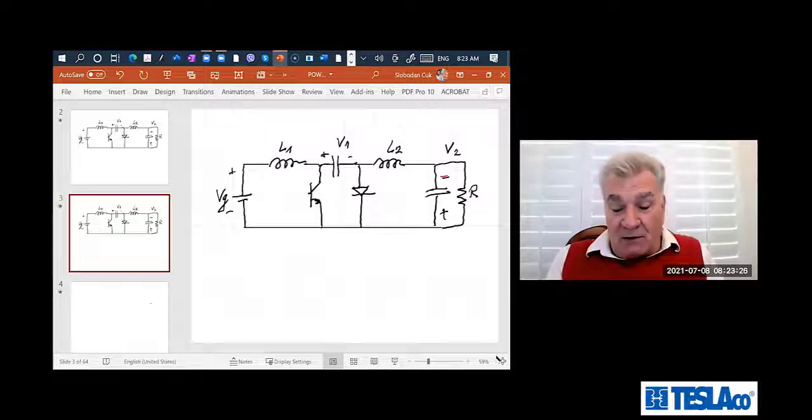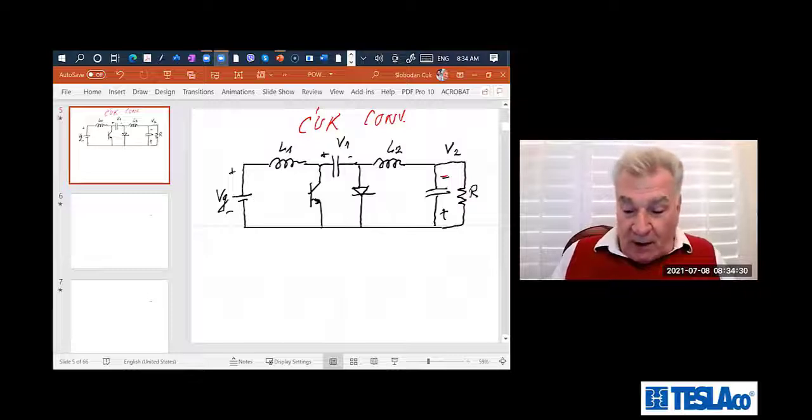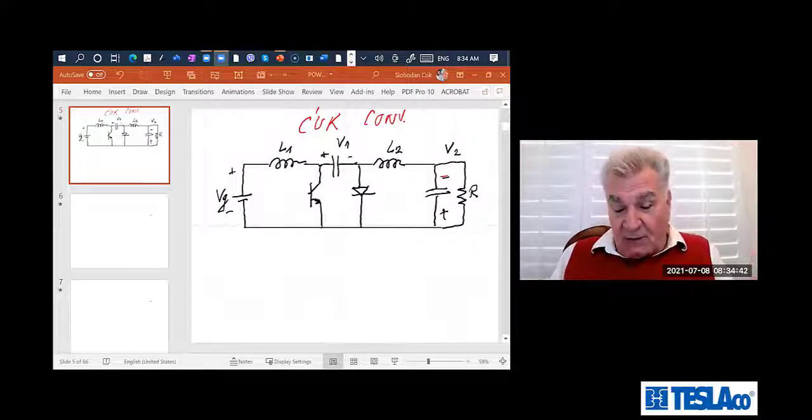Both of them have an isolation transformer, right? All right, so what would you do here? I replace the output inductor with the diode. And that's one version, which ends up as step-up with the isolation transformer, power factor correction, everything in one circuit. Then we replaced the input inductor with the switch and kept the output inductor. So far, so good.